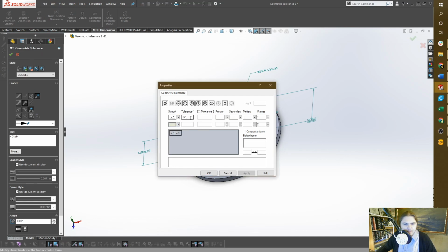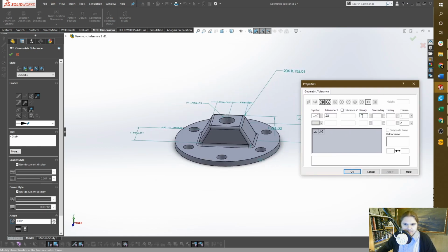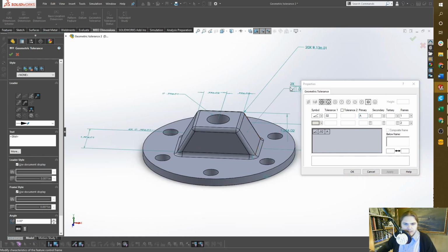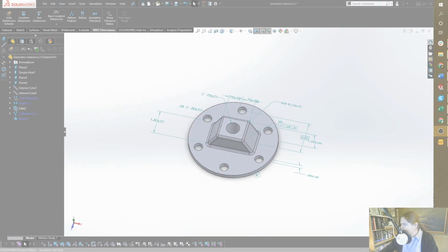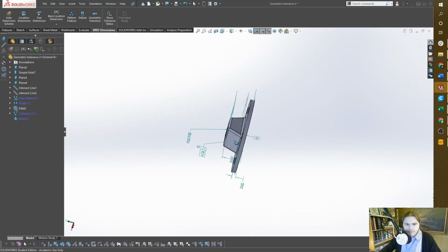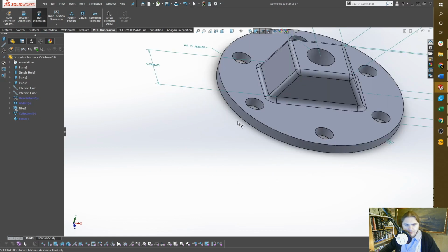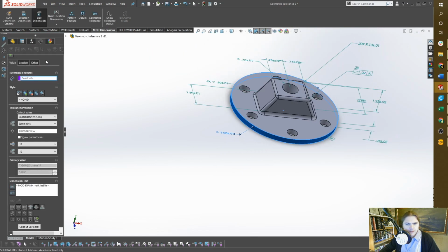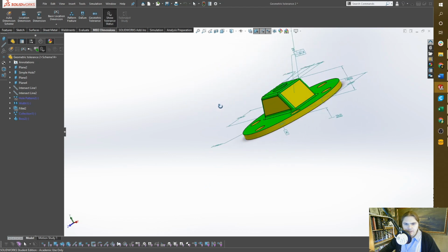angularity. We'll leave it at that, and this will have an angularity tolerance in reference to datum A. Click there and place it. As you can see, it added the 2x on that. Alright, let's keep on going. Looks like I forgot to do the size dimension on the outside cylinder here. And now I think we can start applying some of our tolerances.